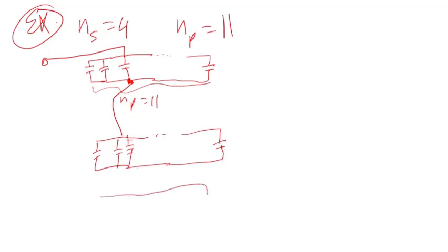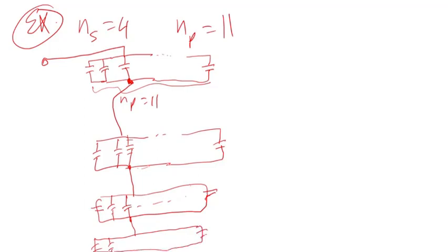So you will do basically 4 of these and they're connected in series. I'll just draw these, dot dot dot. Then you add another one. That's a capacitor bank. So the number of these units in series is equal to 4, and obviously this is connected. So that's one phase. These series and parallel combinations make single phase.